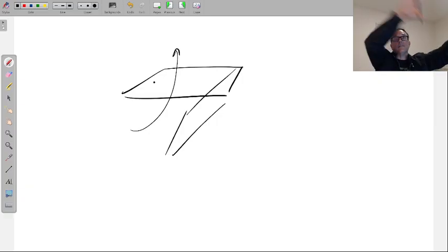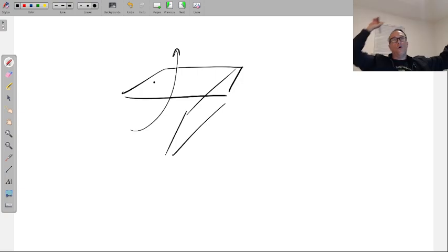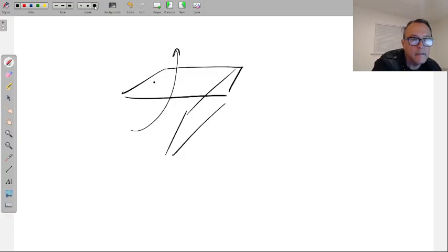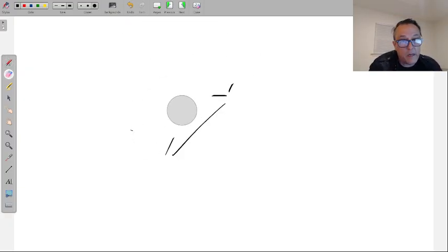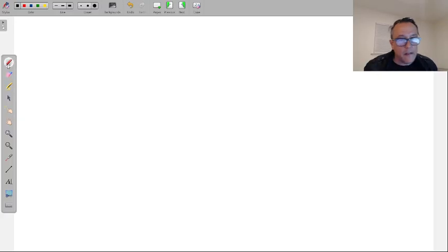And sometimes you see this in the middle of a drywall ceiling. The ceiling is completely drywall all the way around. There's no real way to get into any of the things up there, but they have one of these little hatches tucked away somewhere. Now you can pop that open and crawl up in there, and I've seen this be argued on a job site as to whether or not the inspector feels that there is enough accessibility to junction boxes and other things that have wires in them.